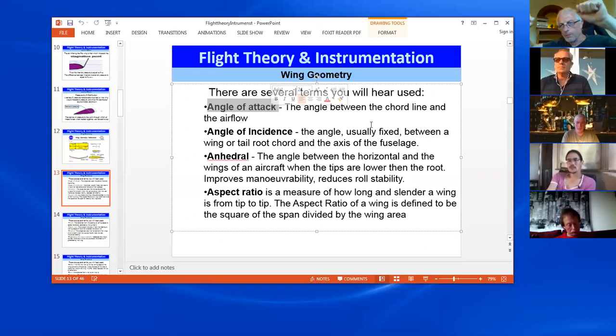If you put brakes on more, then you are increasing the angle of attack. If that's the front of the wing, trailing edge, you apply brakes, the wing's going to do this. So you're increasing the angle of attack. Hands up, you bring this down, put speed bar on, it pulls it down a bit more. You're decreasing the angle of attack. You're causing the wing to go faster.